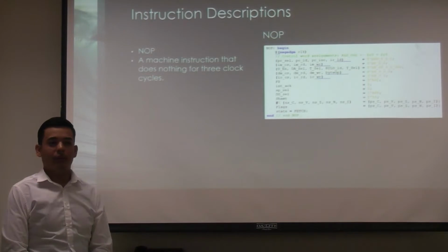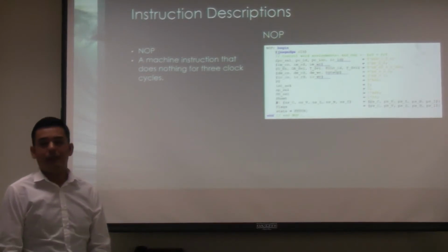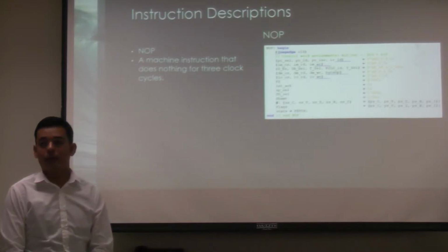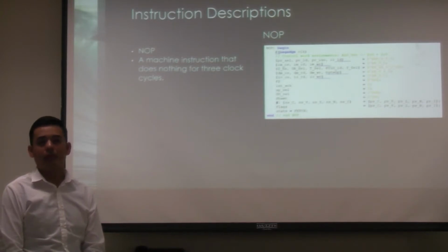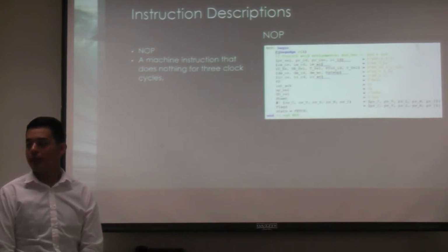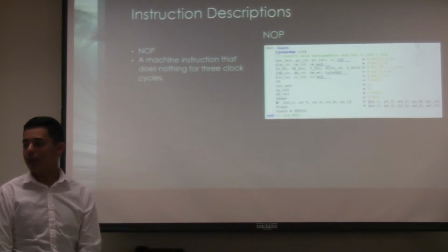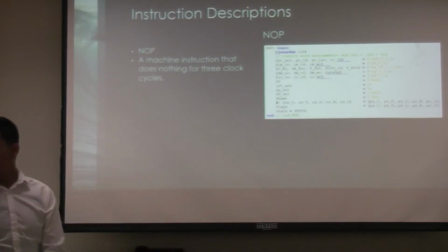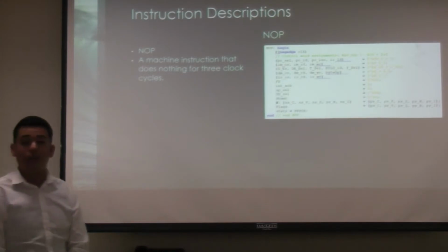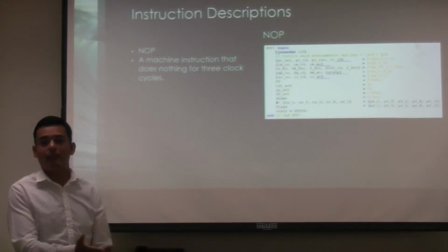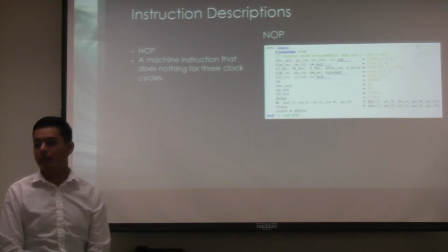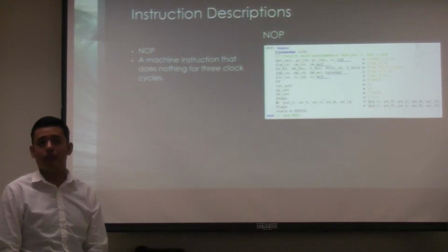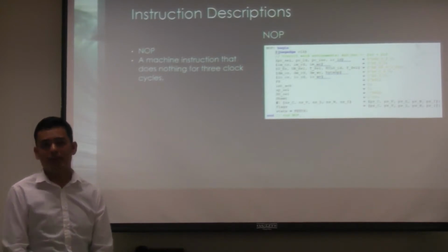And then we also have a no-op instruction. This is a very, very simple instruction, and the reason we implemented it was that every processor we've ever used has a no-op instruction. So we wanted to add that just to be a little bit more user-friendly to whoever uses this processor. All it does is implement an add with 0 as the destination, and as I previously mentioned, if you do an operation to 0, it cannot be written, so it does nothing for 3 states. Any operation that has a write back to 0 is pretty much a no-op.